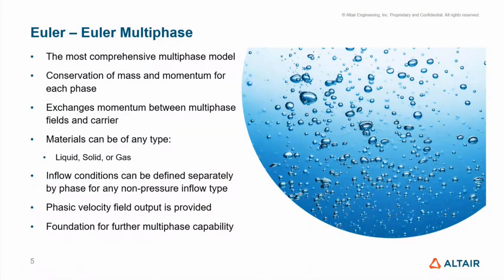As the backbone to AcuSolve EDEM coupling, it's only natural that we would release the Euler-Euler model as its own feature. This model is the most comprehensive multi-phase model where mass and momentum are conserved for each phase, and exchanges in momentum between the individual fields and the carrier field are fully accounted for. Each phase is treated as an interpenetrating continuum where the particles are not tracked individually, but rather modeled as an ensemble averaged cloud.